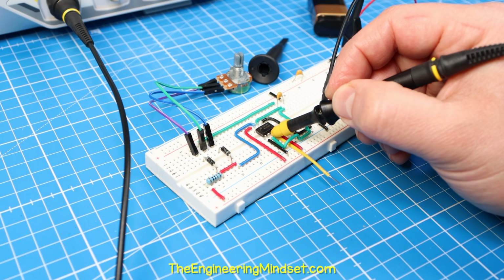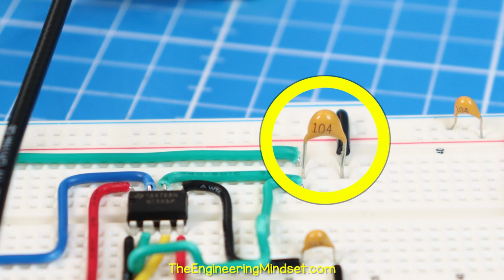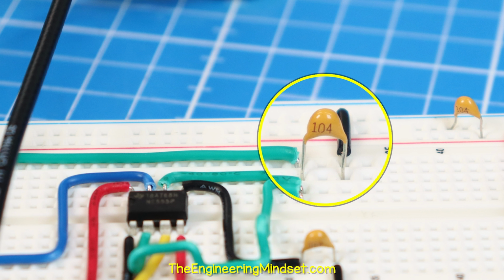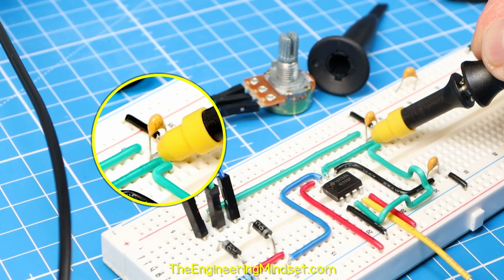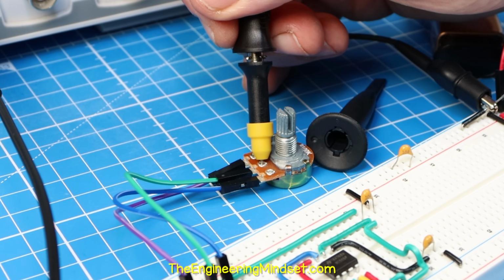Place your probe onto pin 2. You should see a sawtooth wave. This is the charging and discharging of the timing capacitor. We can also see that on the capacitor, on pin 6, or on the potentiometer.